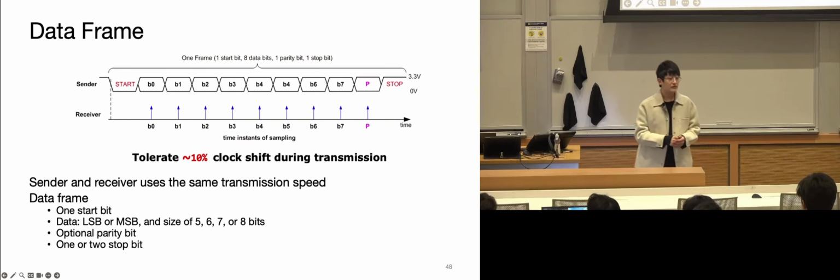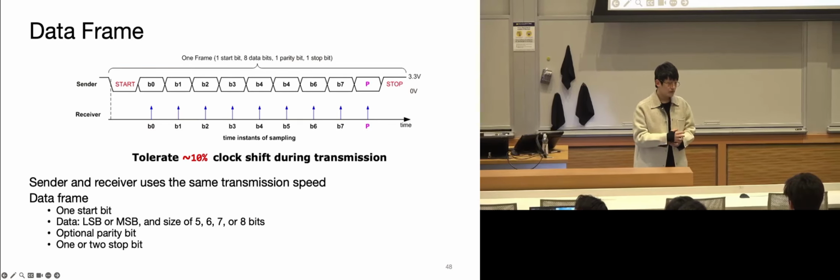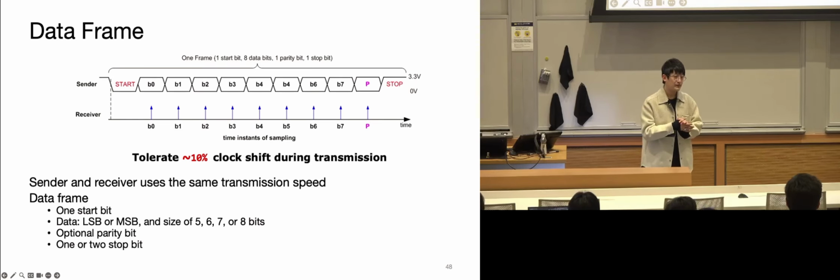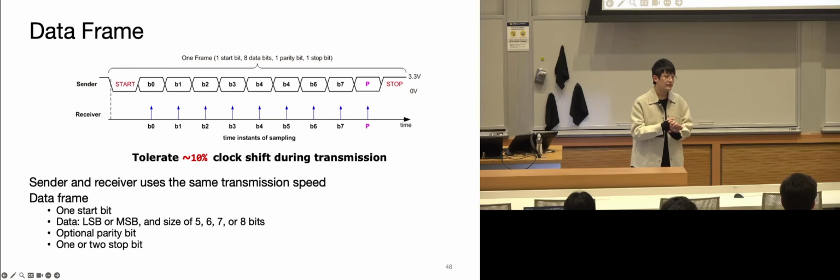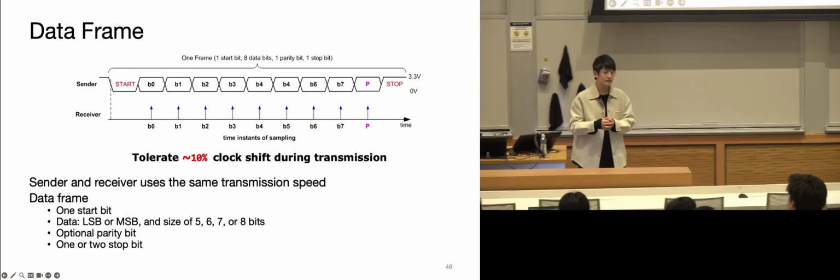is only caused by the difference in the baud rate, right? Because that's the only thing that causes the drift. The oversampling only makes the detection of the edge happen as close as possible to the edge happening itself. Yeah, technically on a well-implemented one, the difference should only be that. So if you have 16 times oversampling, then it will be 1/16 max. But it doesn't alter the drift, like the 10% or something. It just adds an offset that will be in every single one after that. So we want to minimize it.